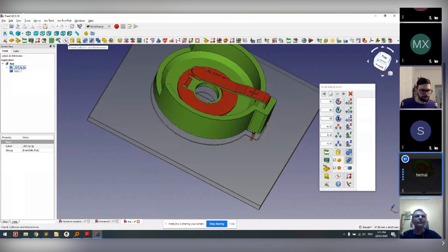What it'll do, it'll subtract these two objects, and it will show you if your mechanical design is interfering with your PCB or the components on the PCB. So that's one of the very helpful features that I've used in KiCad to simulate the design of the PCB, especially when you're doing the placement of your product when a mechanics constraint is there. So I just wanted to point that out really quick.